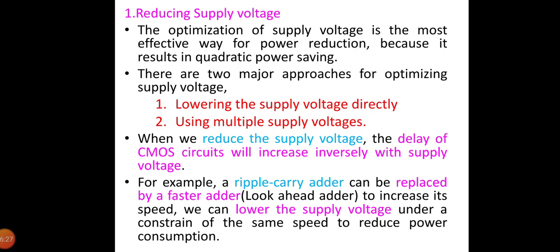The effective capacitance can be determined by averaging the energy over a sequence of random input patterns with a uniform distribution. One way to maintain the throughput while reducing the supply voltage is to utilize a parallel architecture. Two identical adder-comparator data paths may be connected in parallel, allowing each unit to work at half the original rate while maintaining the original throughput.